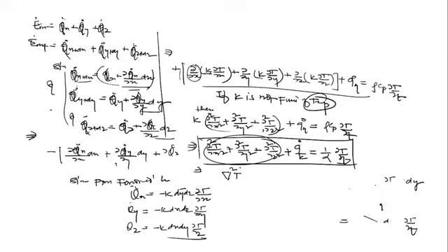Although it's not fully general. This is your general equation, the one before it. One assumption is it's for a 3-dimensional and uniform area, and k is not a function of temperature. These two are very important assumptions in this equation.